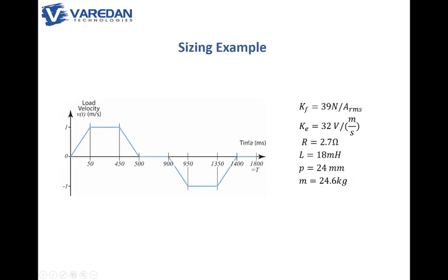And we're choosing a velocity profile that's trapezoidal. This allows for a simple description, and most of the time we can do a good job sizing with a simple worst case trapezoidal velocity profile. We recognize that often these profiles will be rounded with S-curves and so forth, but that will ensure that you're well within the safe operating area of the amplifiers.